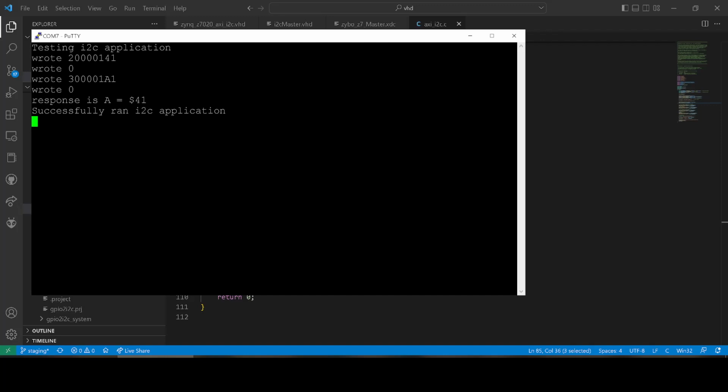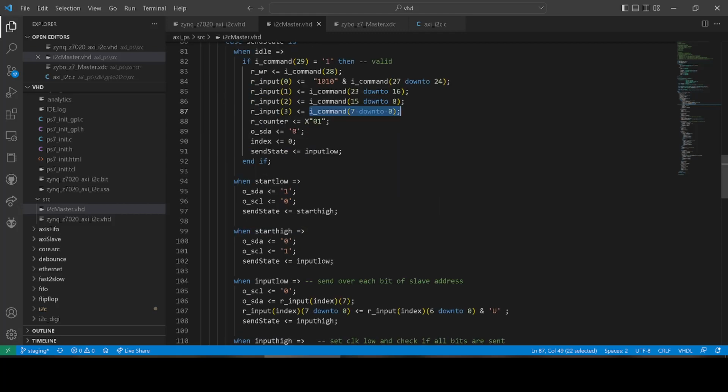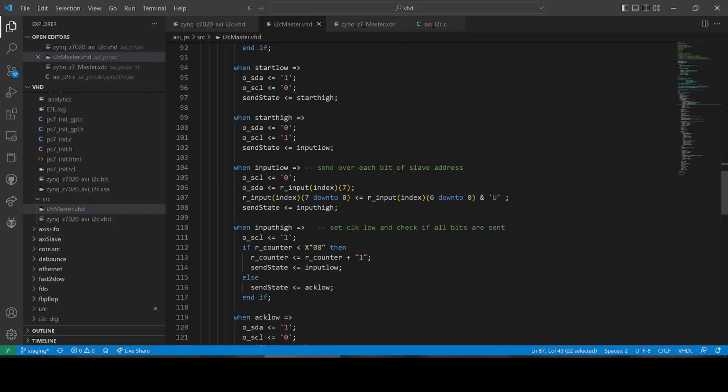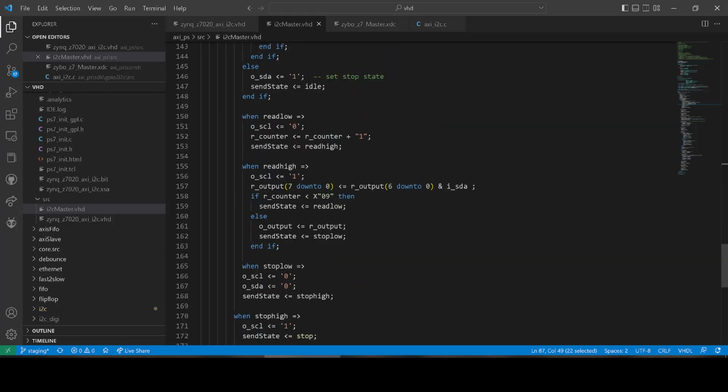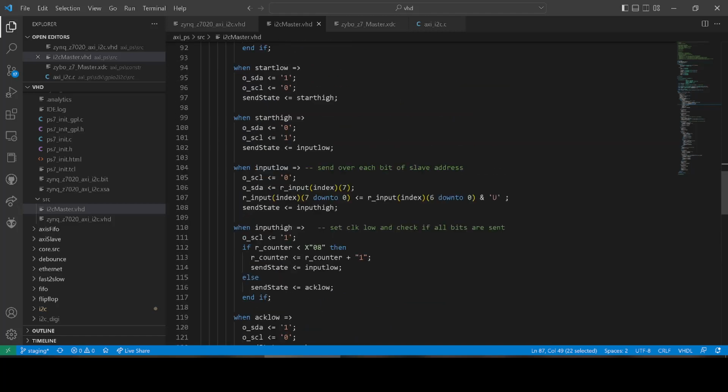I mean, that was more difficult than AXI. I did an AXI bus. That was easy. The timing that was required to do this master code was more complex. In the end, I made it smaller. If you saw the code before, this thing had a lot of states and it was drawn out, trying to get the timing right. And then once I got all that working right, I combined it into basically just a 1 byte